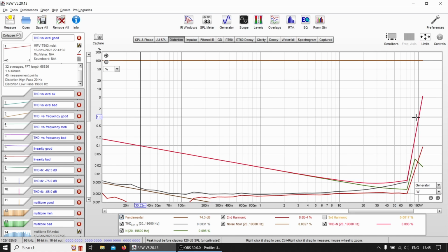And this specific amplifier, if we just cross this like here, we can see that it's doing 100 watts at 1% THD. Now, you wouldn't want to play an amplifier at 1% at maximum volume. That's why headroom is good, because you can see this rise of THD is very, very sharp. If you increase it by another 20, 30 watts, it's going to go up to 5, 10% and even higher. So it's not the best idea to play the amplifier at this much level.